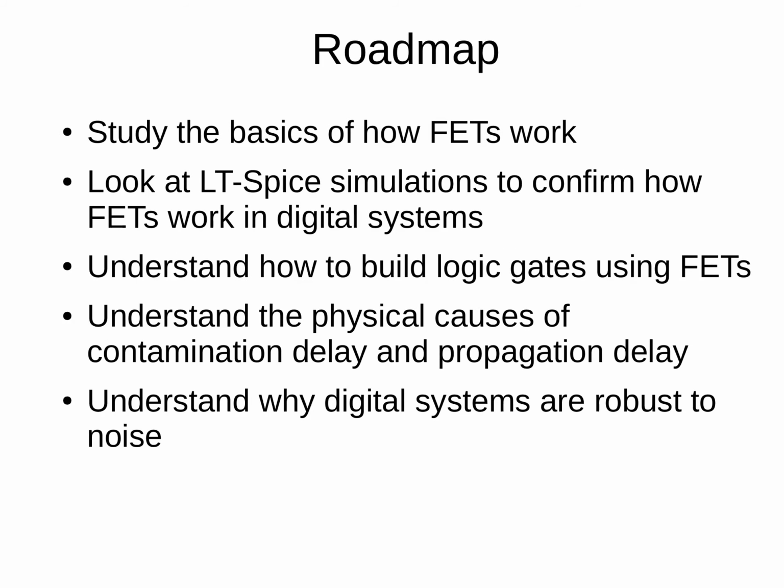In this series on FETs in digital systems, we'll first look at the basics of how FETs work. We'll look at some LT-SPICE simulations to see the typical waveforms we get when we use FETs as logic gates. We'll understand how to build logic gates using FETs. We'll understand the physical causes of contamination delay and propagation delay, and we'll also understand why digital systems are robust to noise.